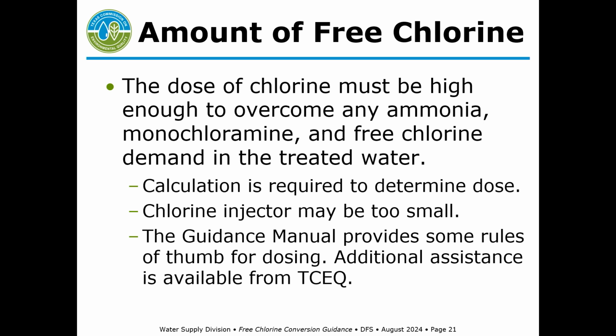You're going to have to do some calculations. Again, in the appendix of the guidance manual, there's help on how to do those calculations. It's not uncommon to find that your chlorine injection system isn't big enough to handle converting the water to free chlorine, but go through the manual, and if you're having trouble figuring out, hey, is this working or not, feel free to reach out to us. We can help you with that.